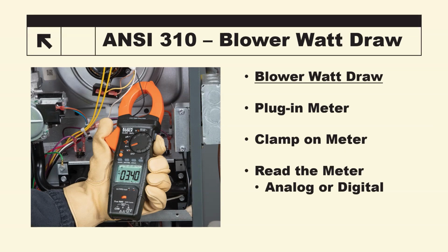It's an air handler system, or just the air handler for a furnace. It has a pigtail on it and it's plugged into an outlet. Those things can be pulled out and a kilowatt meter put in. You plug the system into it, and you're able to run the watt draw and measure the wattage through that.